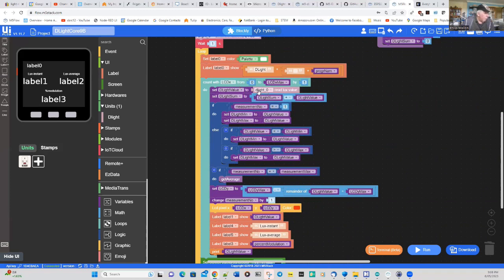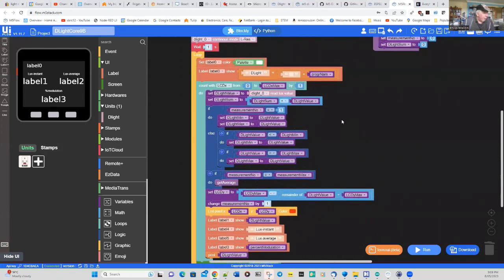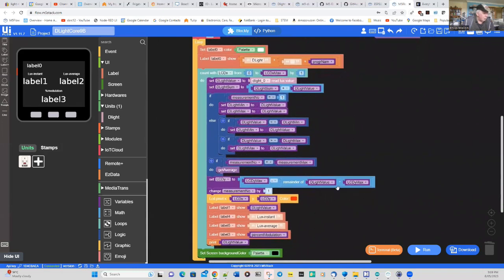We go along the screen. We're going to scroll and set up a graph on the Core LCD of the instantaneous light value that we're measuring. And here we're actually measuring the light and collecting the values and calculating. After we've finished the cycle, we then go and calculate the average value. And when we get the average value, we can then get the minimum and maximum and display all those measurements together with the percentage modulation.